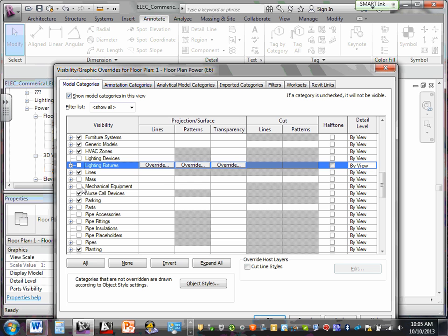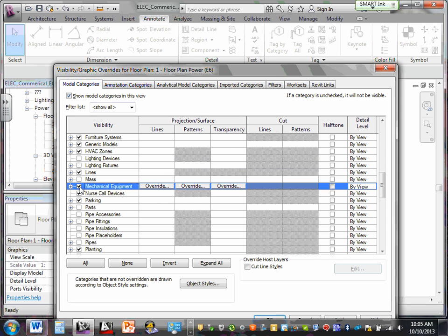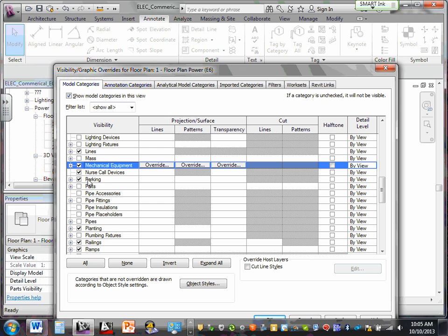Now, mechanical equipment. Interesting. Click the mechanical equipment, will ya? It's unclicked. We're going to be dropping air handling units. And if this is unclicked, the air handling unit will not show. It's a mechanical equipment, so make sure it's clicked. Everybody's following with me, guys? Yep. Brian, Karen, everybody's following? Okay, click that mechanical equipment.